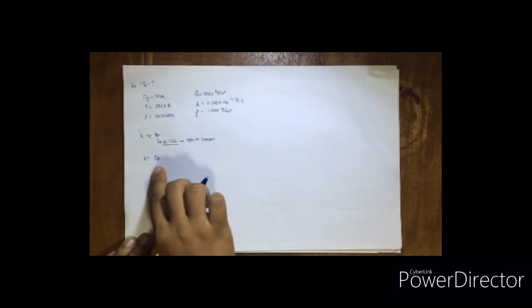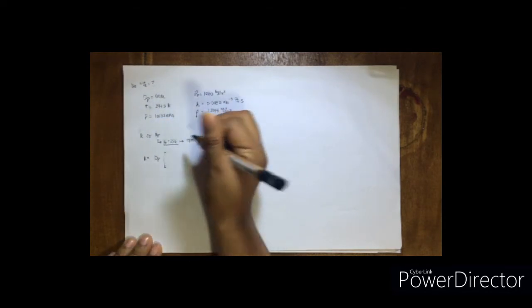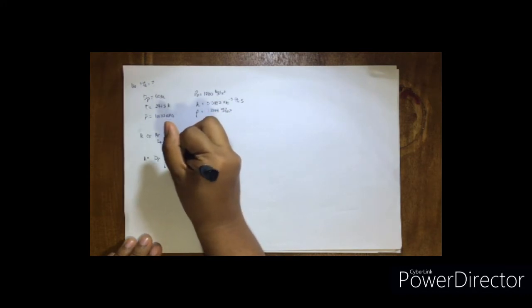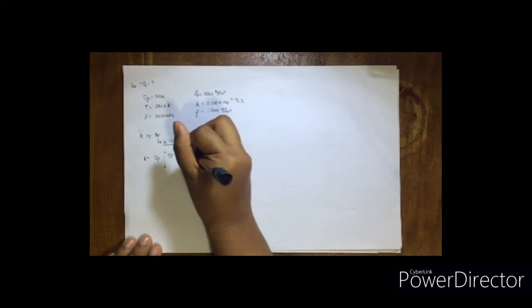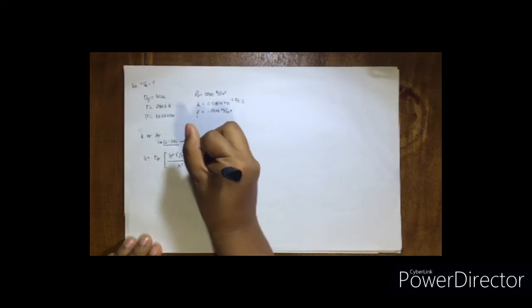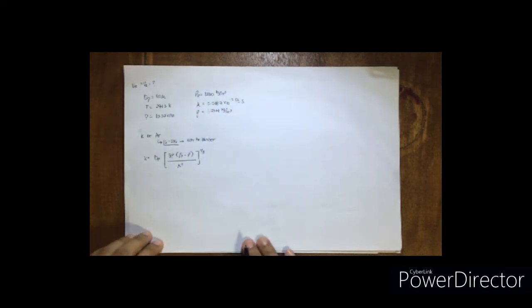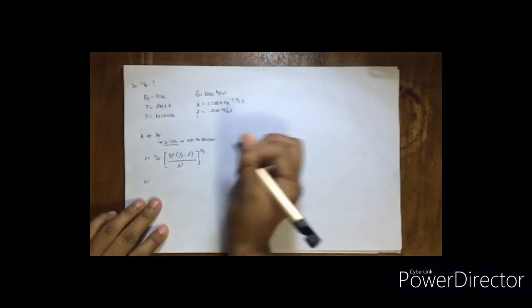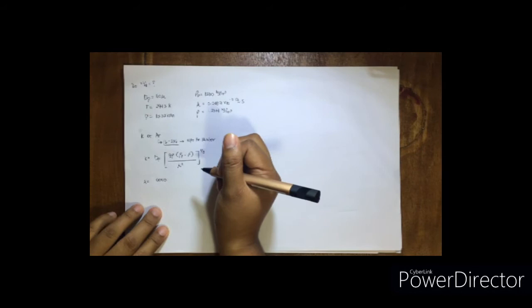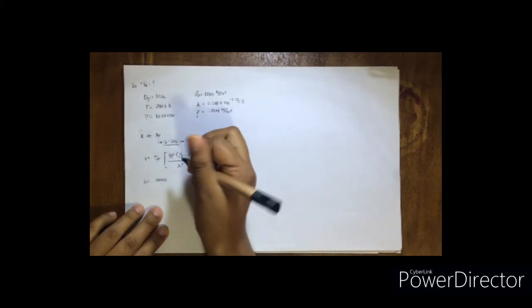This is the particle diameter times the cube root of the gravity, the density of the fluid times the particle density minus the density of our fluid, divided by our viscosity squared, all raised to 1/3. So let's substitute the necessary parameters to find the value of our K. Make sure all your units are in SI, since we are using SI units here.